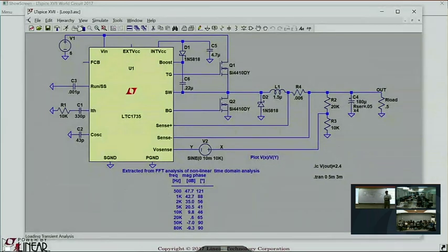And that is where you get into these proprietary slope compensation functions. I said that in Analog Devices, we don't use triangular ramps. Basically this triangular function here avoids a high frequency instability due to all the nonlinear waveforms going on, something that's quite outside of frequency domain analysis. That's the thing it's solving.